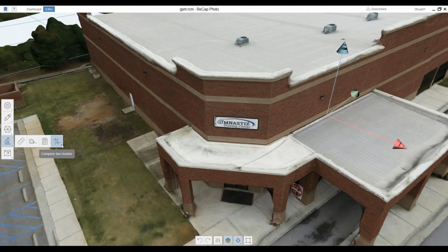In terms of the two models, if you had two models where you took a scan, this is very, very applicable when you're taking progress models. So every week, maybe you took a photogrammetry of the building. You can compare that it was at this level last week, and then this week you can see that the walls have been generated maybe a meter higher, and it'll compare the two models, highlight that for you, and show how it is. So it's a very effective managing tool as well if you're looking at it from a construction perspective.